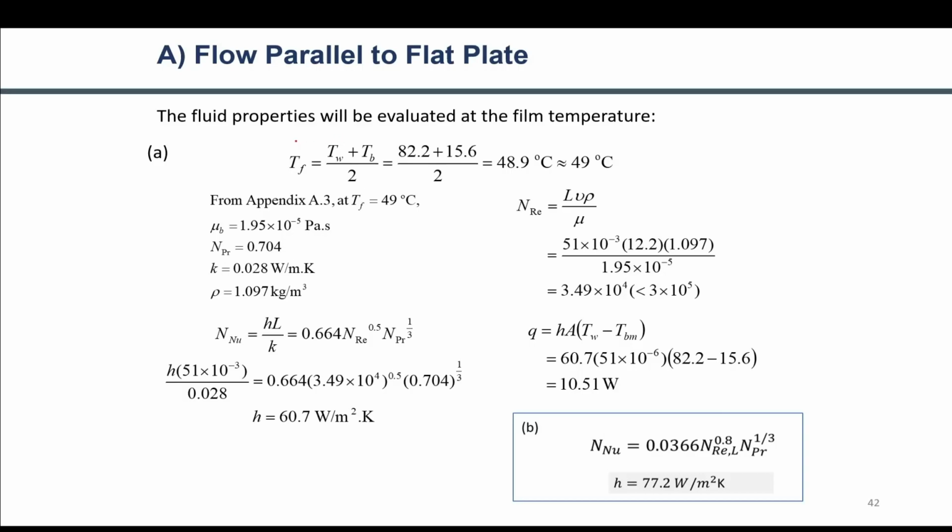But first we have to evaluate the fluid properties at the film temperature. The film temperature is Tw plus Tb divided by 2, so it is around 49 degrees Celsius.